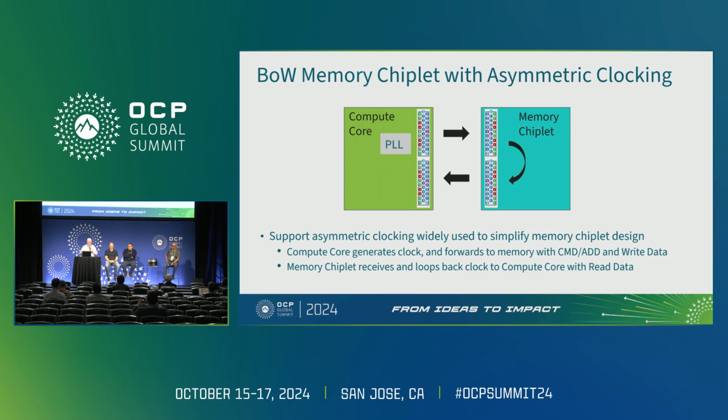In addition, we're looking at the third use case, which I said is just a memory chiplet brought up onto a package. There was a question earlier about, well, what other kind of memory chiplets are we going to do that aren't this extreme, terabytes per second bandwidth? It is, I think, widely known here in this technical group. Memory chips are built on different processes than logic chips. Memory processes are older technology, slower, and have different optimizations in order to improve the memory bits.